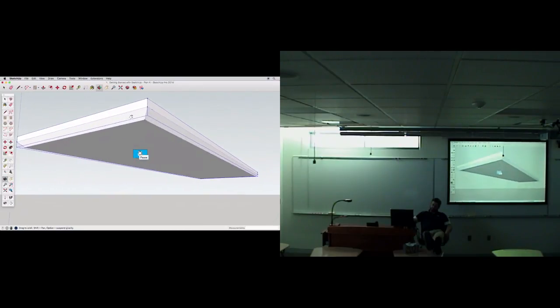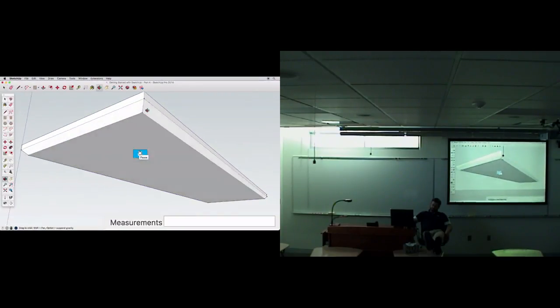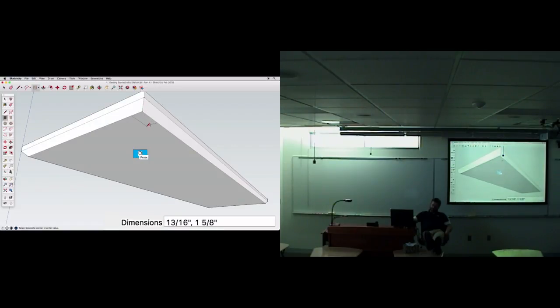And it now behaves as a single, unique entity. Draw the leg rectangle again. Make it 2 inches long, 1 inch deep from the corner. But this time it won't merge with the edges.